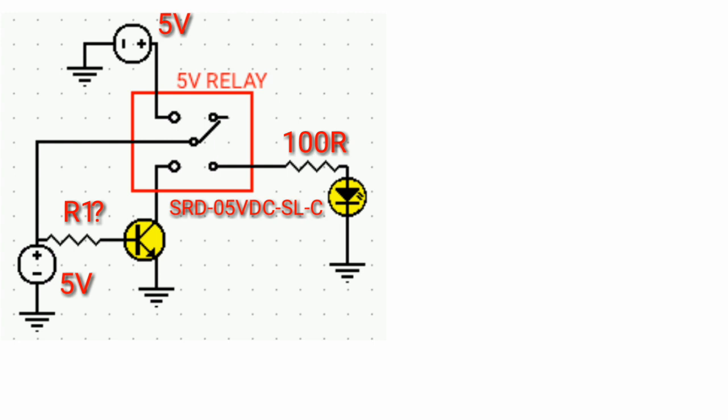Now, let's discuss how to calculate the transistor using BD139, and the main component of the circuit is transistor. The work of the BD139 transistor is to drive the relay switch, the positive 5V of the battery connected to the coil of the relay switch, and the opposite coil connected to the collector of the BD139.